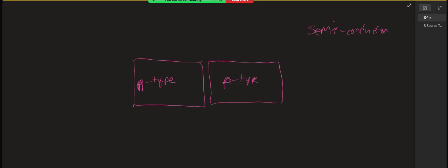And the way that they conduct is by the electrons. They have some free electrons that can move, and when they move, they leave behind a hole. And that hole acts like a positive charge carrier, and the electron is a negative charge carrier. But all in all, it's not charged, because you still have the same amount of positive and negative. It's just that you have these charge carriers that can move. And good semiconductors are silicon, germanium, gallium arsenide, and some others. They're pretty good, but if you dope them, then they can act better.